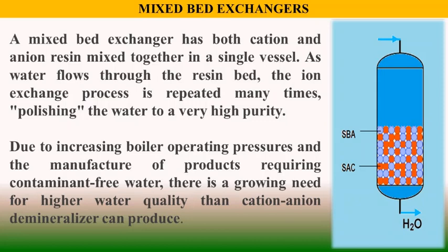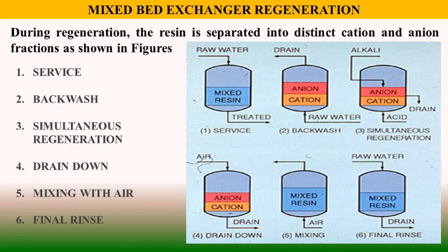Due to increasing boiler operating pressures and manufacture of products requiring very high quality water, during regeneration the resin is separated into distinct cation and anion fractions.